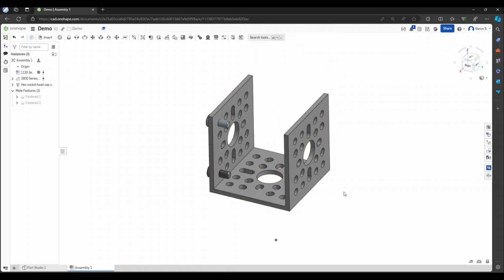And what that does is that now it's fixed and it'll show that to you right here. Part is fixed. So now if you were to grab and try to move it, it would just tell you nuh-uh because it's fixed. So it fixes its position in the assembly and not relative to anything else. It is actually just stuck there. So that's pretty much how to use fix.